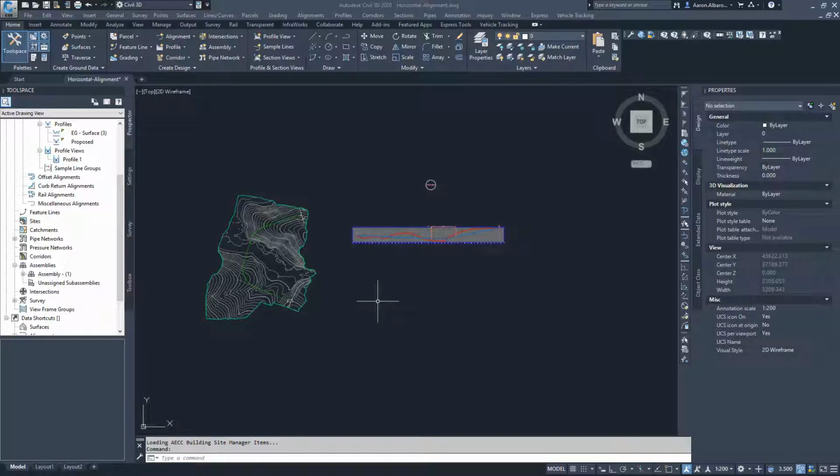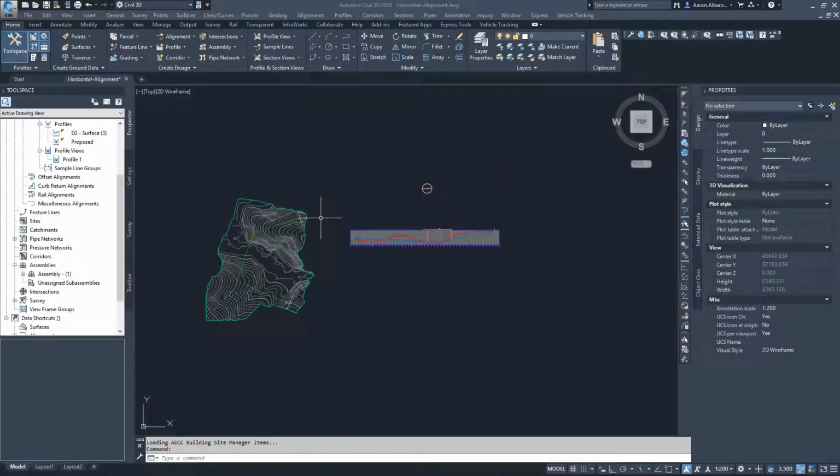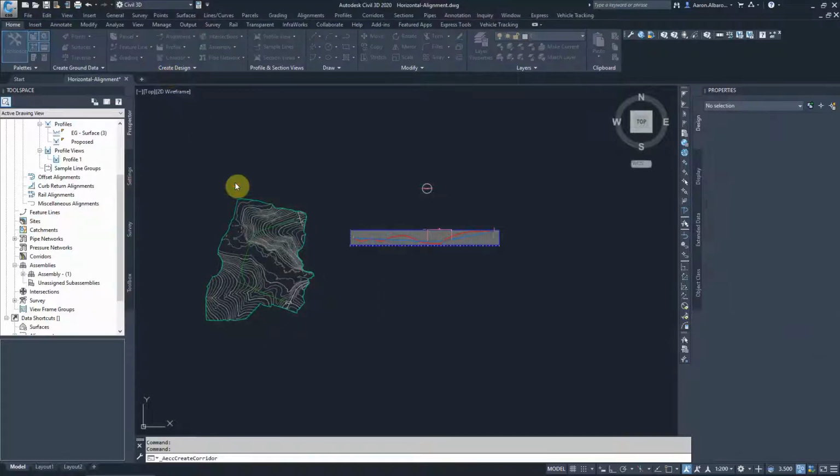We created a cross-section configuration for our road in 2 dimensions. At this point we start creating our road corridor that will combine all these components together. We start creating the first 3D assembly of our road. So to do that, we go to corridor creation.